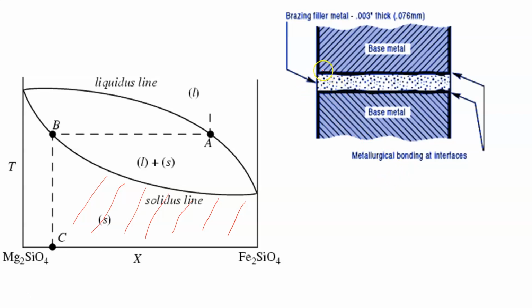Now, when you bring things in for brazing and soldering, there's a certain amount of clearance that you expect to have between the two different materials. So what happens is that the molten filler, the molten brazing material or soldering material, is drawn into the clearances through capillary action. And it's that capillary action that draws it in, creates your bond, and sets it up. And again, this is usually a much lower temperature process than welding of any kind.